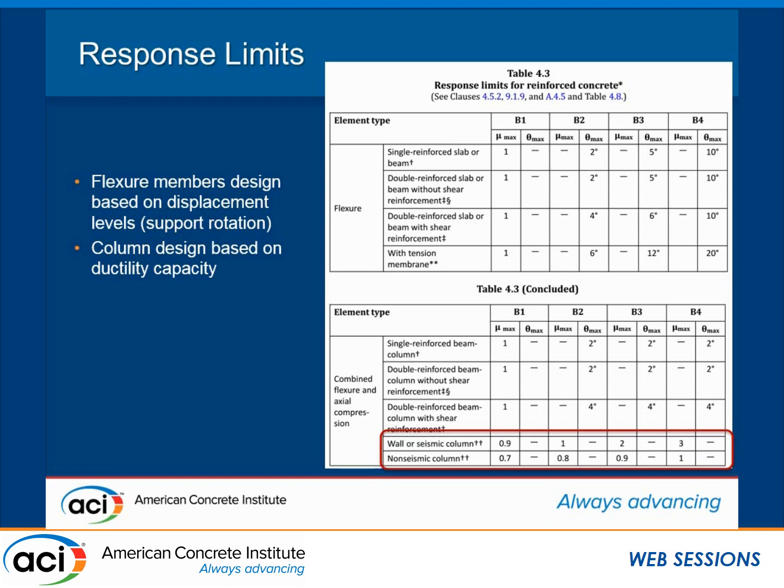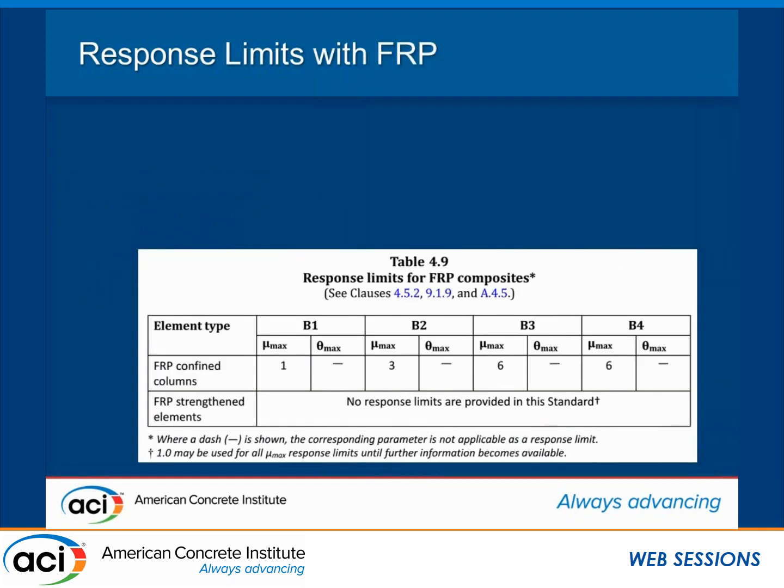Whereas a seismic column, if we can design to that, we can start to gain some ductility capacity out of this and push it a little bit further. And roughly speaking, we can say that these ductilities would be proportional to a displacement-based design at that point. Very roughly, if we can design to B1 at 1 or B2 at 1, this is twice the displacement and 3 times the displacement. Very roughly. So columns are, if we do appropriate seismic design, we can go a bit further.